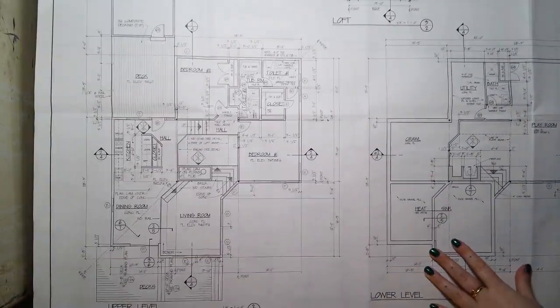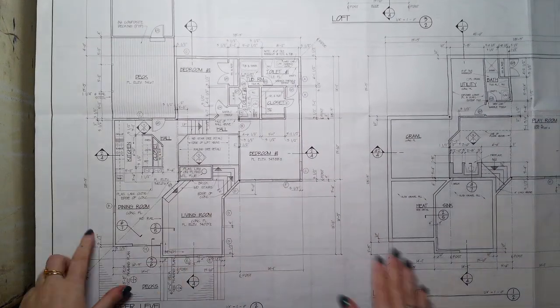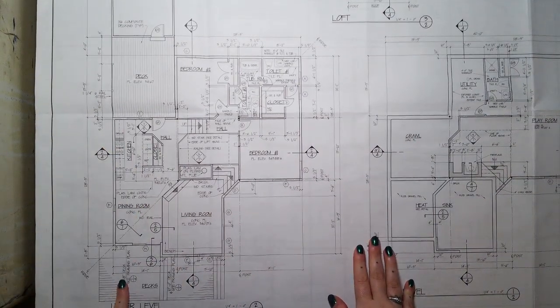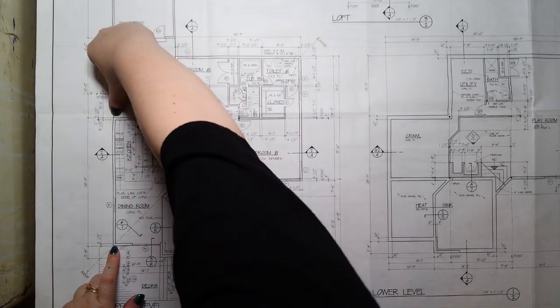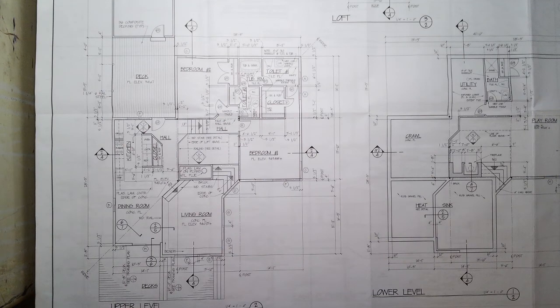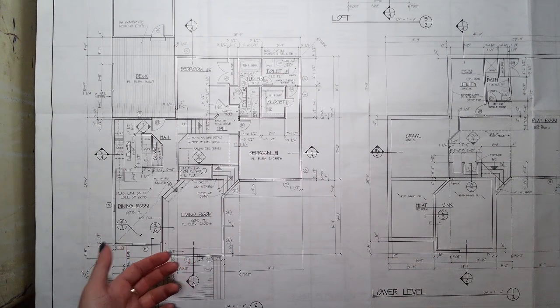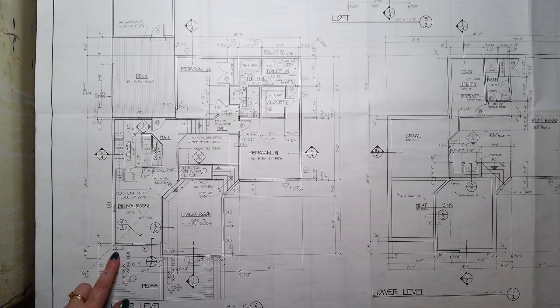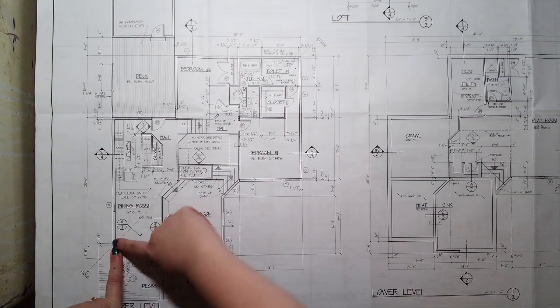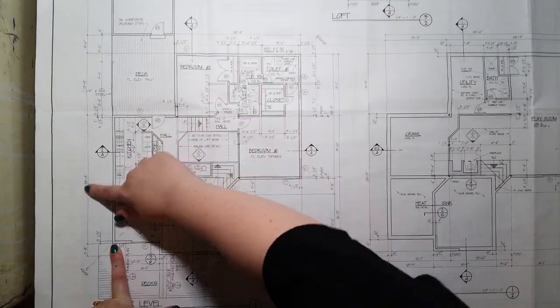So if I'm looking at this floor plan, I need to start thinking about where these measurements are coming from. It's going from the outside of the wall to the outside of the wall, but that's to the outside of the frame, not necessarily with the materials added in, which as the builder is a good thing, because then I don't have to do the math of subtracting the sheathing and whatever exterior siding is on here. I can just think about, okay, I need to frame this wall out to be 28 feet and 3 inches.